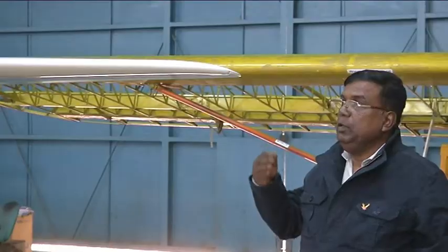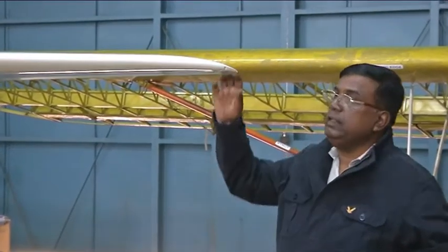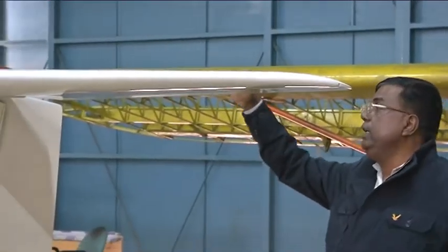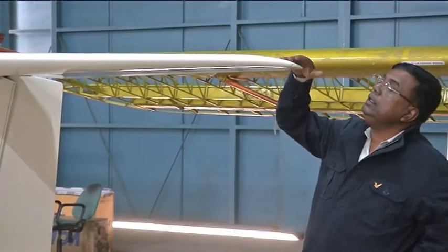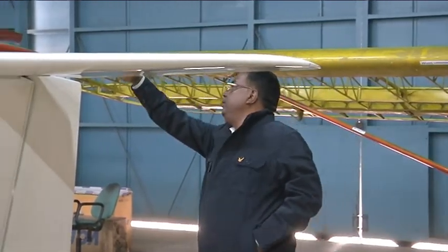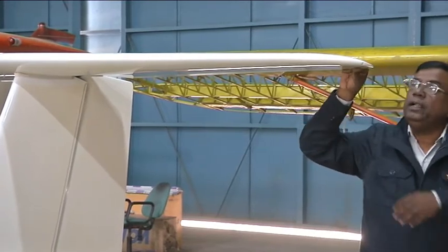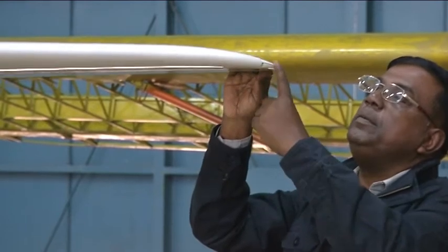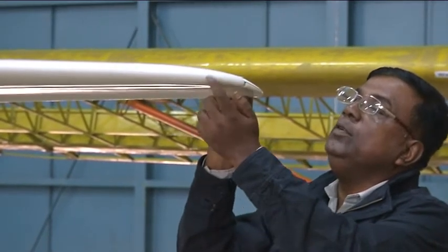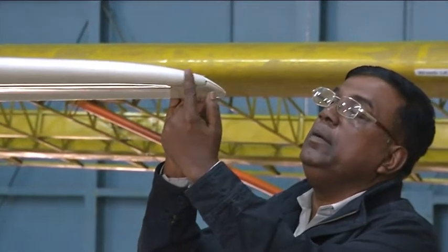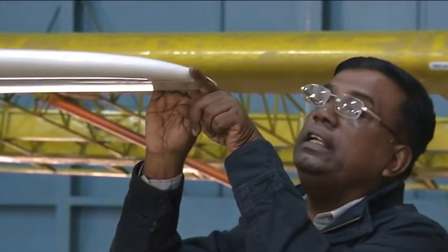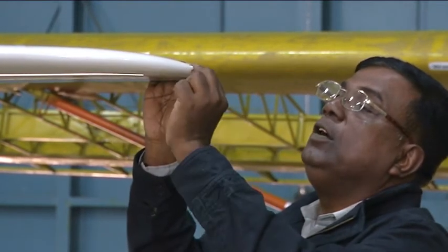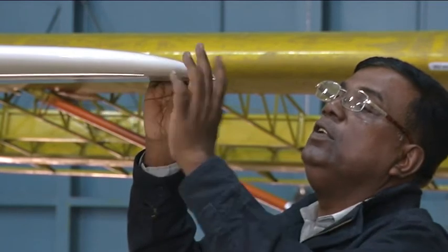I'm repeating the same explanation using the Sinus 912 motor glider. Concentrate here. This is a typical T-tail configuration, and you can see this is the horizontal tail from here to that side, and this part is the elevator. If I put it down, what happens? Initially it was completely symmetric like this. As I put it down, it is as if it has generated a camber, or we say the zero lift line has changed. If it is symmetric, the zero lift line will be along the chord, so if alpha is equal to 0, there won't be any lift.